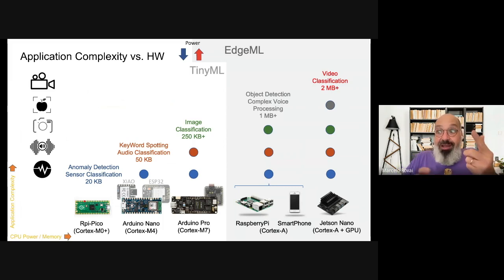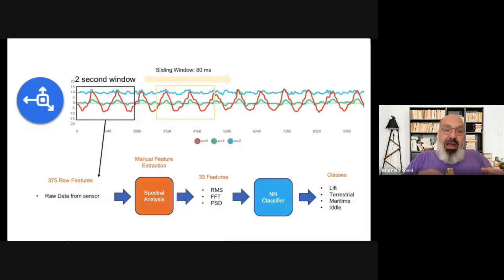You should always remember that when we are talking about movement, or you are working with accelerometers, or temperature, that kind of time series data, usually you make a conversion, a pre-processing. You take this serial data that's moving in time, and use a window. You take a piece of that signal and convert it to a group of numbers.